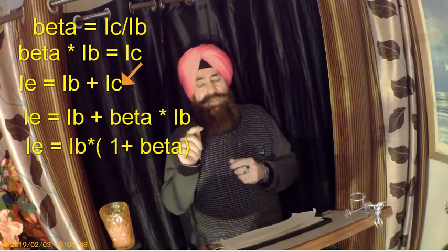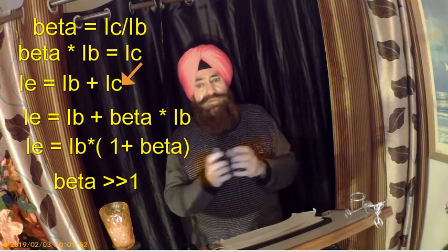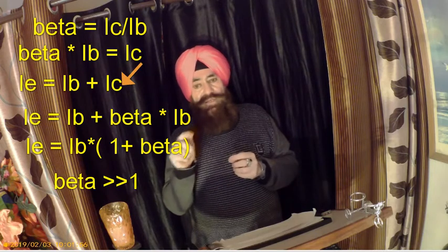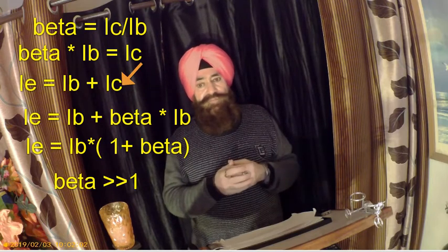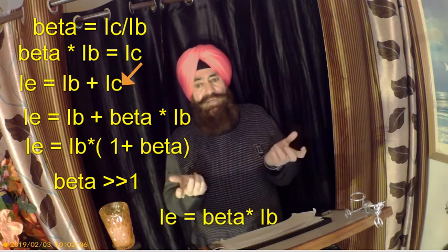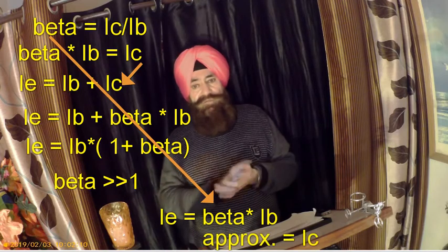As beta of a transistor is very large, if beta is greater than 1, the 1 may be neglected compared to beta. So that becomes simply beta IB. And what is beta IB? It is IC. So IE is approximately equal to IC.